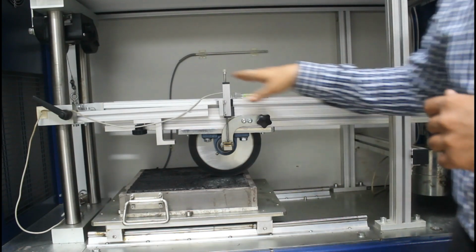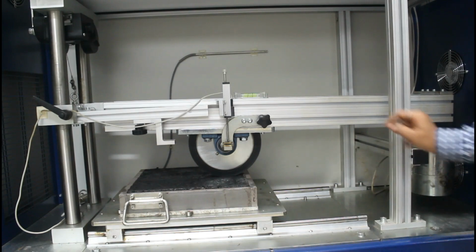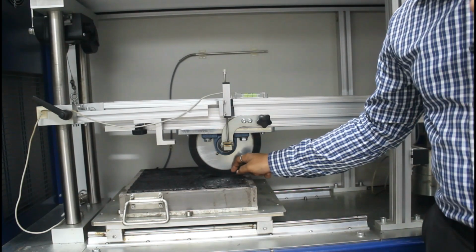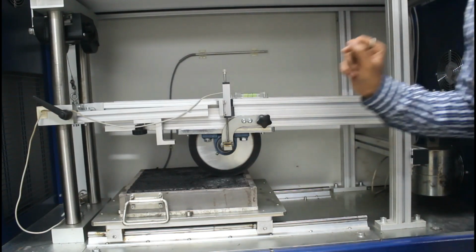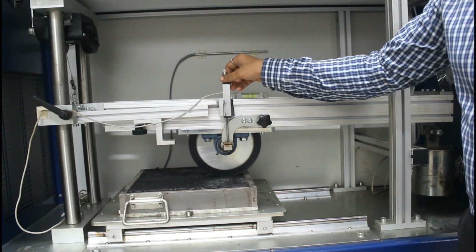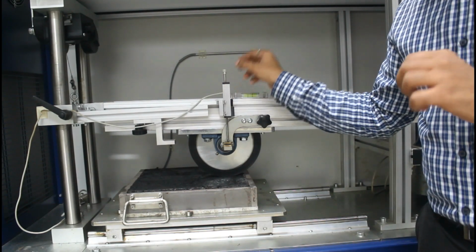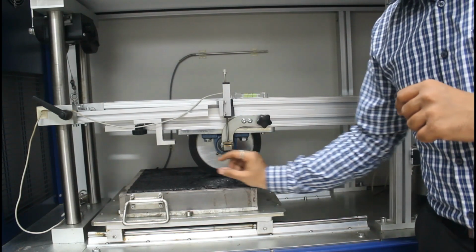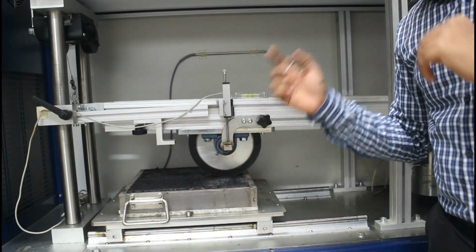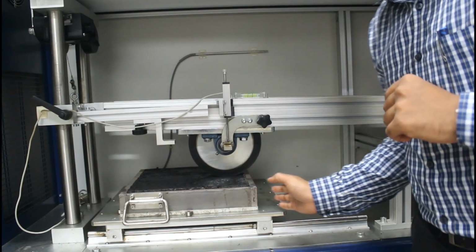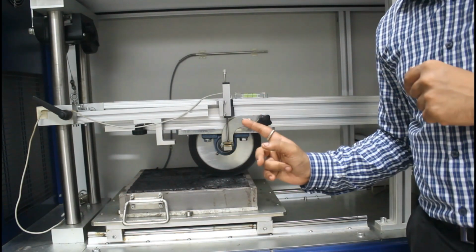So now this particular cantilever beam, right? The loading is here basically at this point. At this point, the load is around 70 kg or 700 newtons, and then there is an LVDT. Now this LVDT, or linear variable displacement transducer, will determine how much depth, or how much rutting, is occurring at every cycle, right? One cycle means one to-and-fro motion. That means one like this and come back.